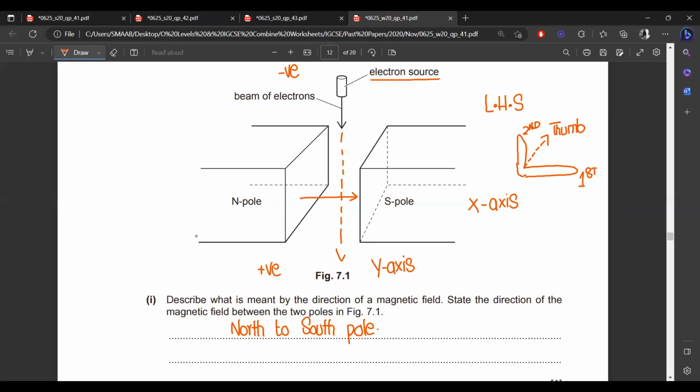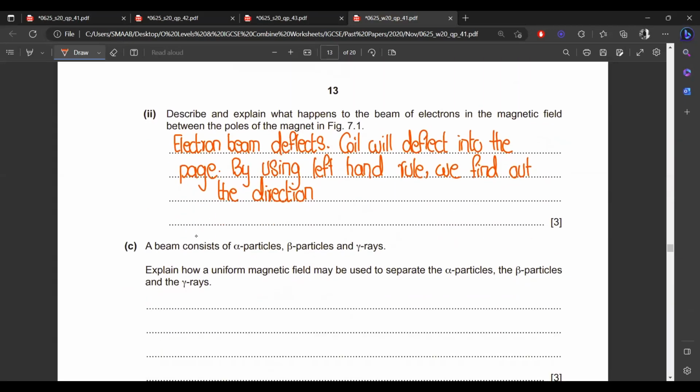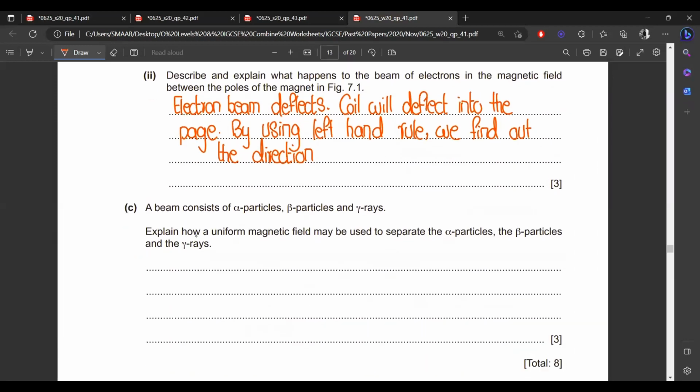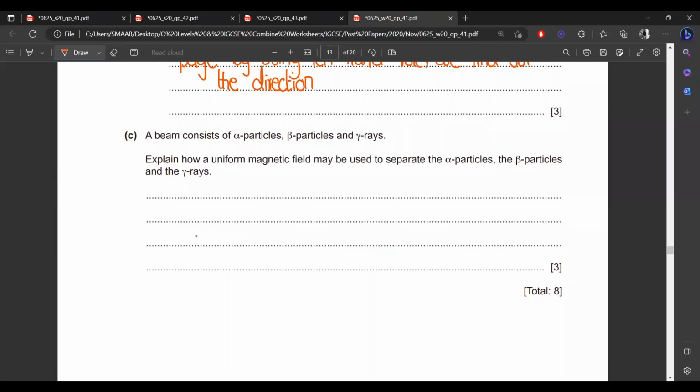Or just you find out the direction from the negative side and then reverse the concept, because you know that current will always flow from the positive side. So if we are getting out of the page when current is moving downward from the negative side, so it means when current moves from the positive side, we will get the direction into the page, right? Right, sir. Any confusion? No. Because sometime it will be difficult to rotate our hand in the direction, because this is not our regular practice. So you may continue with the same negative direction, then reverse the deflection, because current will flow from the positive side.